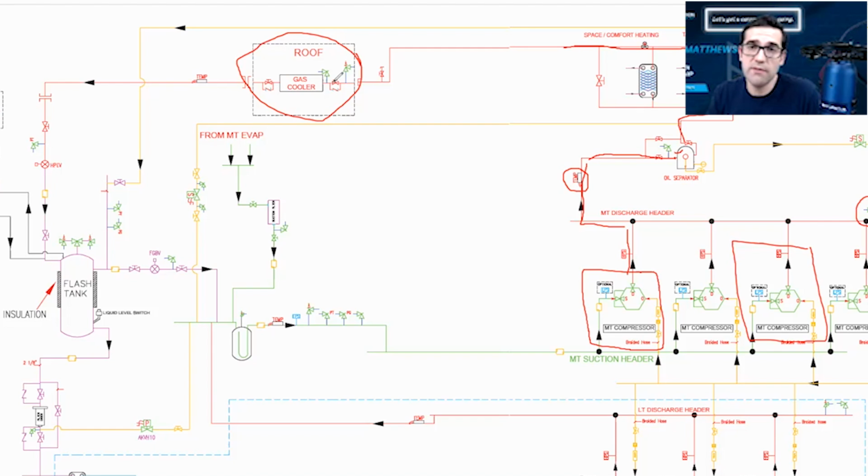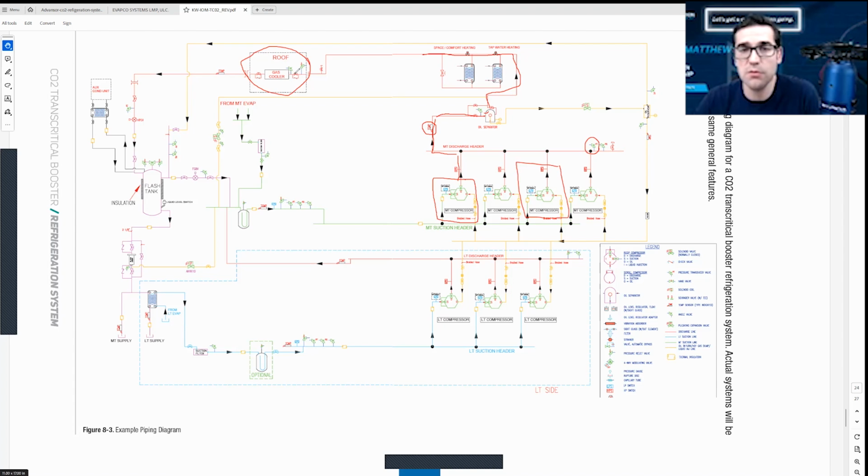There needs to be more, even on the HFC side. There's so many systems running out there inefficiently because there's no recommissioning done. Taking this old piece of equipment and making it run better. Because there's so many end users out there that think, well, it's running, it's keeping everything cold, it's fine. Well, no, it's costing you an extra 50 grand a year because you're not setting up the superheats. You're not adding a drive to the rack. You're not getting a new controller. You got an old Comtrol or RMCC on there. There's upgrades for a reason, to make your systems more efficient. Cleaning the coils, just the basic ones I see out there, is costing end users so much money. And this is where it can change, by you telling them about it.